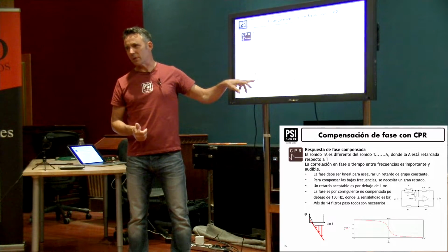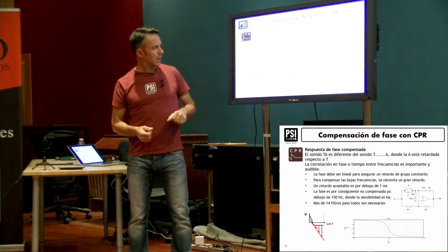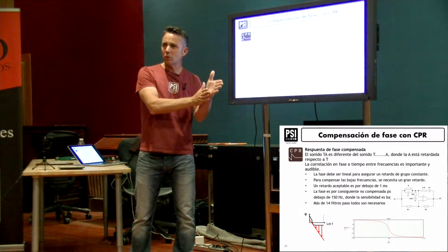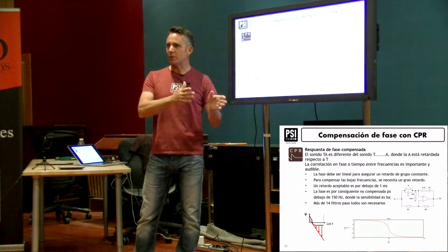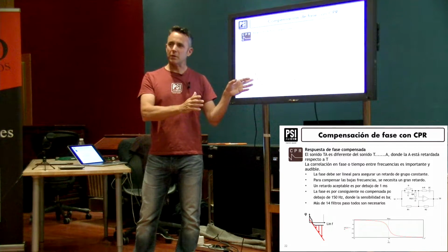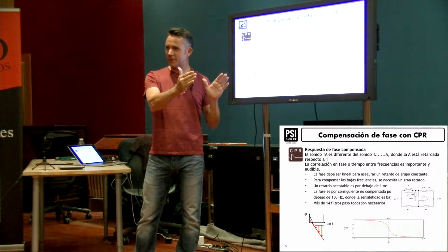So we're looking for a linear phase response. You can have a linear phase response that goes down very low, down to 20 hertz, but the problem is you're going to have to wait a long time, and that creates a lot of latency in the system.